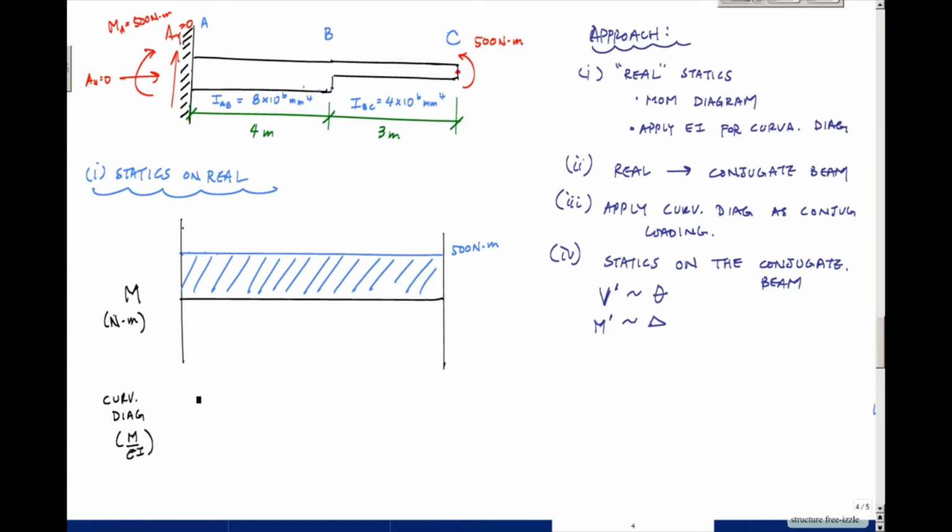I have a large moment of inertia here compared to segment BC, so you would expect your curvature to be less, because you have more resistance to bending. So I would have it up to segment BC, right there, segment B right there.